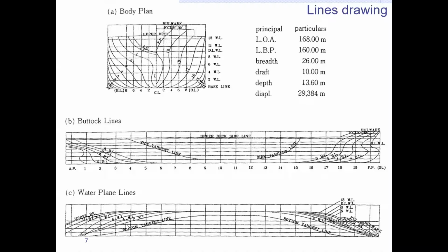And the waterline is here, say waterline 6, at the body plan. The 6 waterline is from the bottom, it is number 6 waterline. If you cut the ship at this waterline, the sectional shape from the top view looks like a curve like this. So that is the way we describe the outer skin shape of the ship.